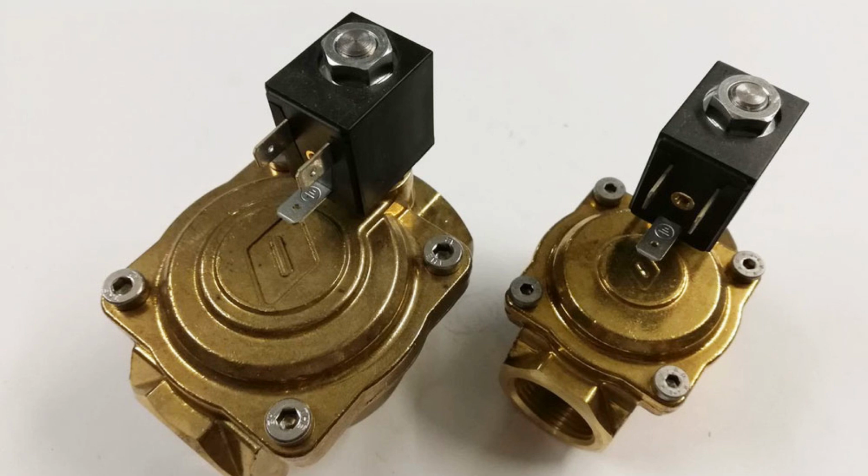A little more about what solenoids are in a car. You can also call them an element of controlling the operating modes of the automatic transmission. Structurally, there is nothing complicated in this device. It is a rod made of metal and wrapped with a special spiral through which a direct current flows. Inside, this special rod is movable. Under the influence of the incoming current, this rod moves with the help of a spring from the end of the existing spiral to its beginning, thus timely closing or opening the flow of lubricating fluid.